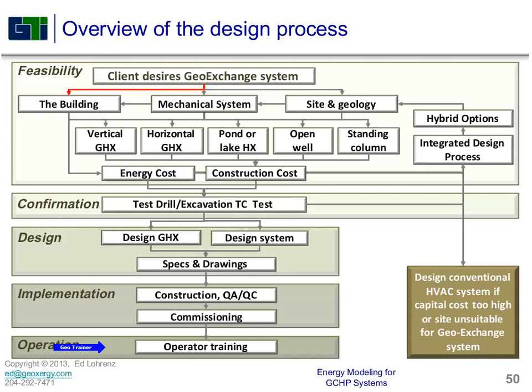Yeah, and Ed, if you don't mind me sort of chiming in here. The best way to reduce your drilling requirements is to get your energy modeling right, such that you can figure out how to balance your heating and cooling loads that are going into and out of the ground. When you can figure that out, that's the best way to ultimately reduce your installation costs for your loop field.